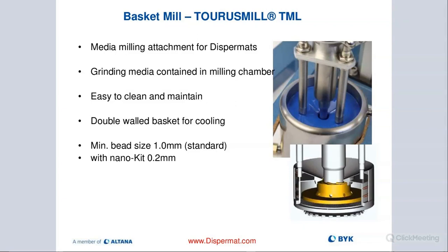That chamber is filled with beads. When you're milling, that milling disc is working really hard to get these beads moving inside of that milling chamber. And if the screen was on the side, the media would impact the screens very, very often, very quickly, and very hard. That means you have excessive wear of your screen because of the design of the mill.